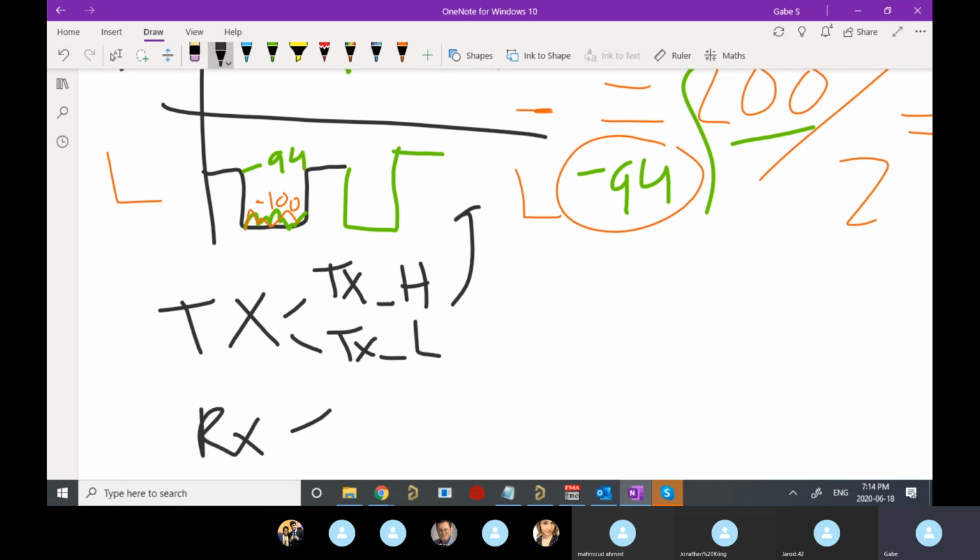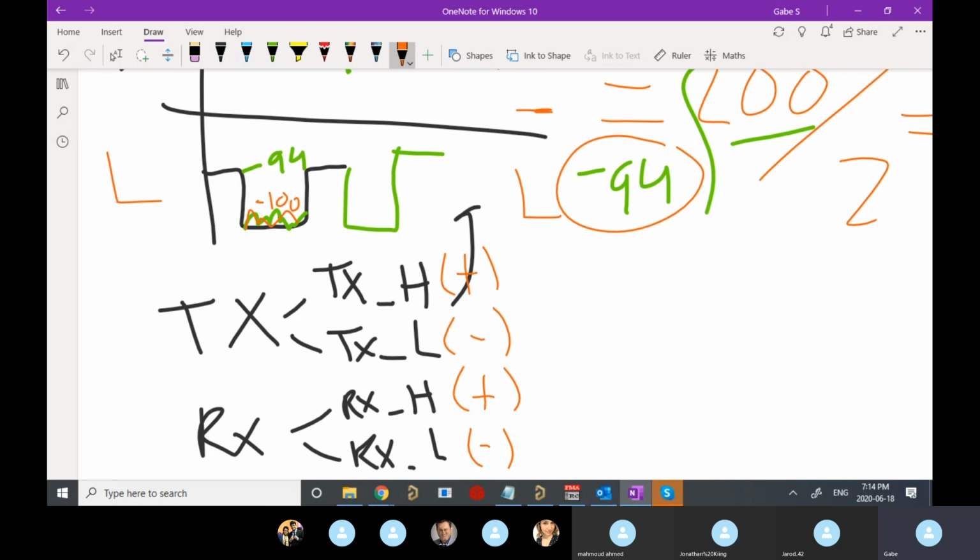So with each of these, we do the exact same differential communication to make it super robust. That's why. Differential, you collect the same noise on both, and then you subtract them, and the noise goes away. We actually do that with the daisy chaining between BMS slaves as well. And sometimes people call these plus and minus instead of high and low. High and low is usually specific to CAN, plus minus is not. So wherever you can do that differential pair and then twist them, you'll get a really robust signal, which is important for BMS.